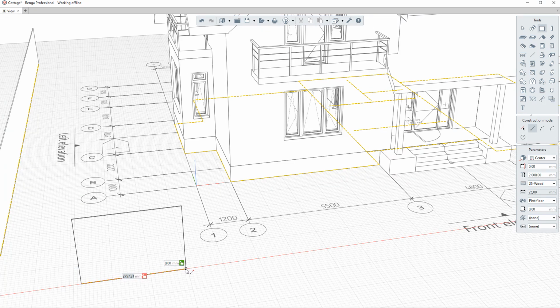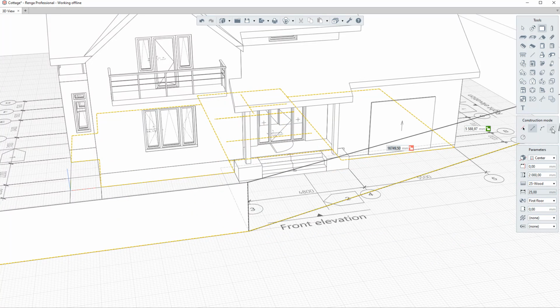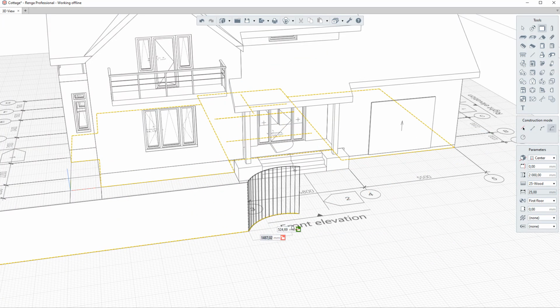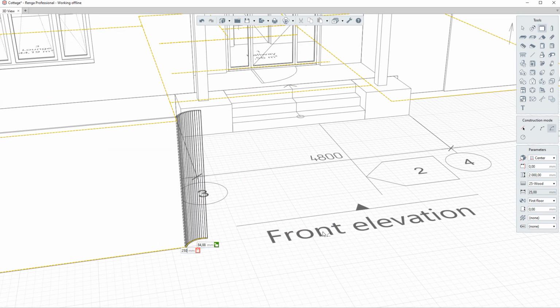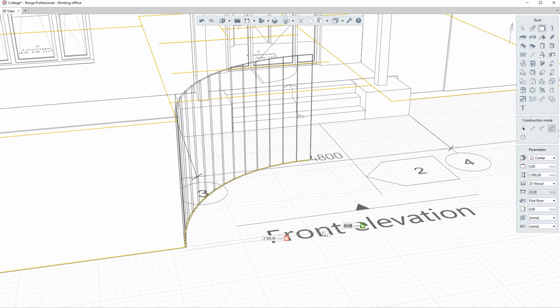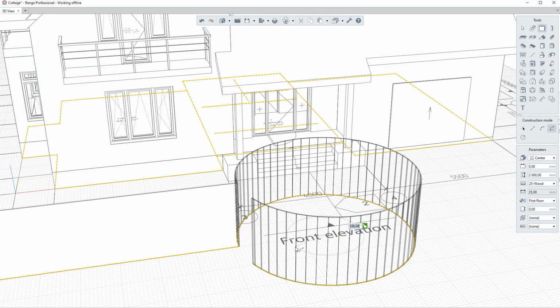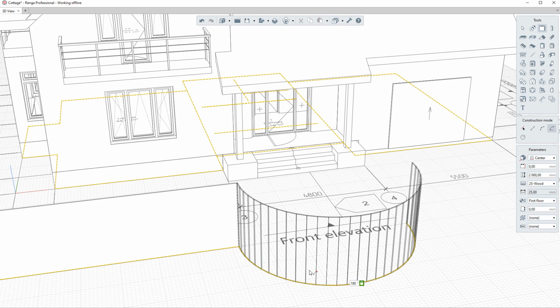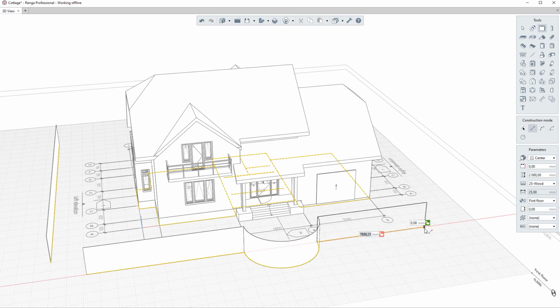Continue to build the wall. Set the value along the red line 10,000 mm. Fix the position. Then on the right panel change construction mode to arc by specifying start, center, end points. Set the value 2,500 mm along the red line, switch to the second field and put 0 mm. Fix the wall position and set the angle 180 degrees in the appeared field. On the right panel change construction mode to line by specifying 2 points, and set the length 10,000 mm.